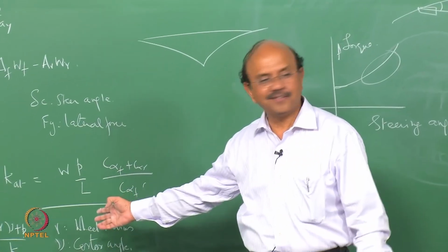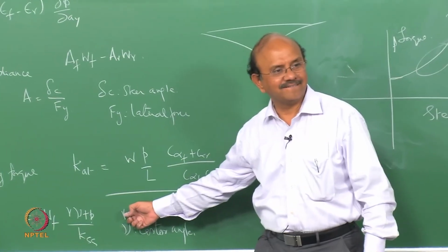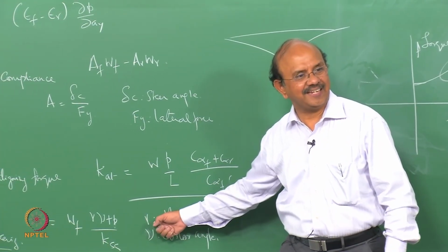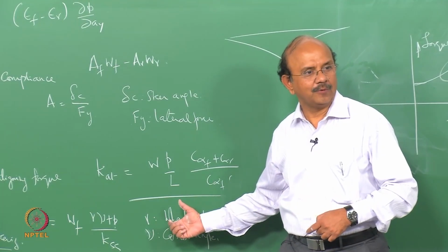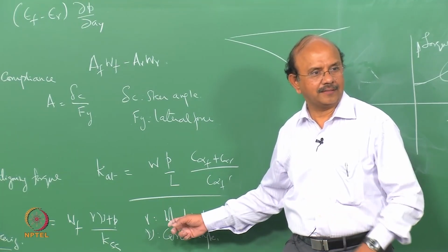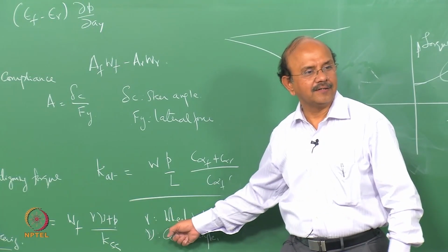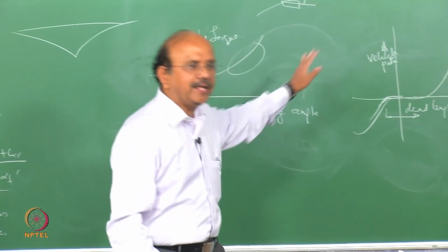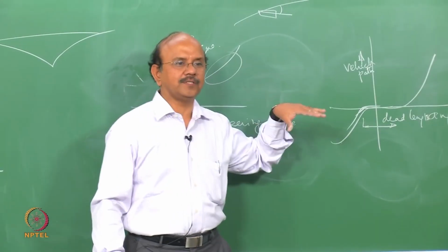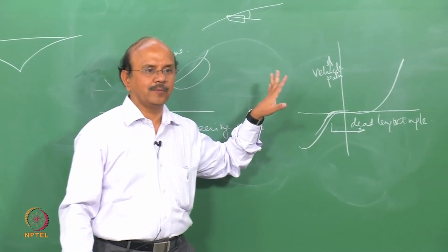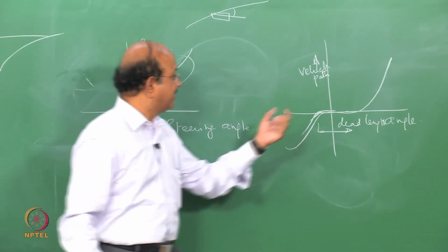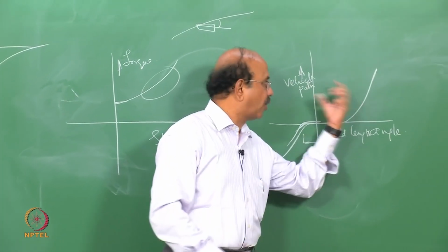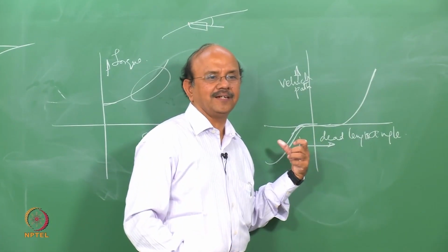That is why we have this here. So that's what we said, that the K steering has an effect. That is why we have one effect. So in other words, in a broad sense, steering has an effect on understeer and oversteer. Clear? But this dead zone is not understeer characteristics. It is the compliance which affects the understeer characteristics.